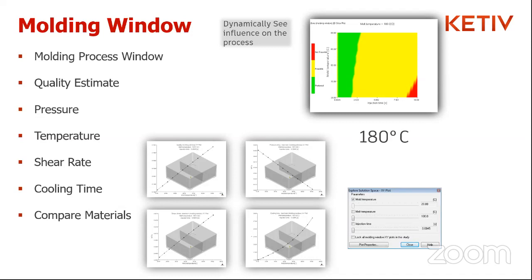You see there is a portion of it after a certain amount of time that does kind of transition into the non-feasible region. And so we start to look at all these different quality plots at this point, right? So whether that's going to be pressure drop, whether it's going to be shear stress or cooling time or temperature, whatever that may be.